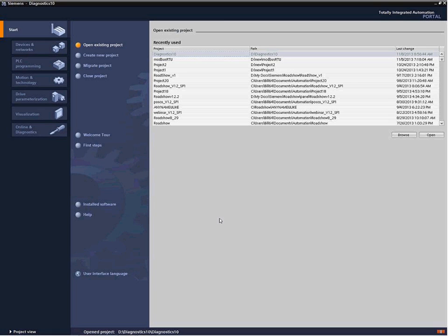And where every time you come back into the plant in the morning, they say it went down again last night, not sure when, not why, but we had to restart it. And the tools we use for that are things like diagnostic logs and online buffers that can look at the status of the tool on the machine and the PLC and so forth, and log and timestamp everything for us. Now, historically, we've had to write stuff like this. The Siemens products actually have these built in, so it's automatic to see what happened in the past.